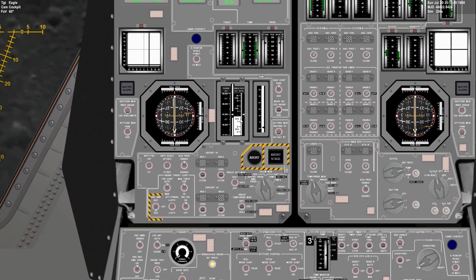The other thing that's needed for a landing is mark interrupt or keyrupt 2, which is the interrupt that the nav DSKY uses in the command module. But for the lunar module, it's just other switches. It's called mark interrupt because it's used for marking things, but also it's used for the ROD or rate of descent switches, which are needed for P66.